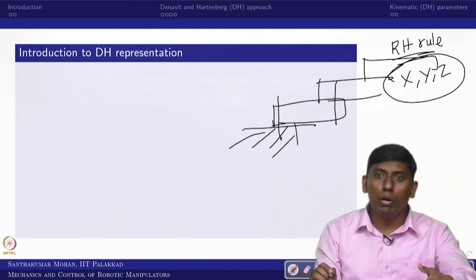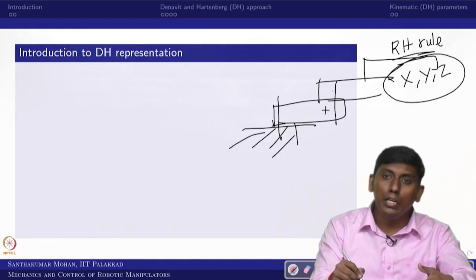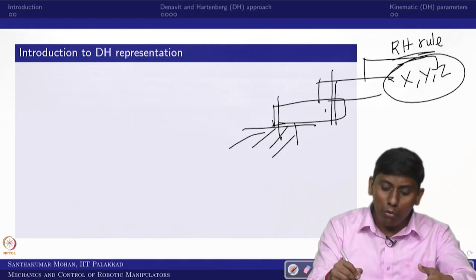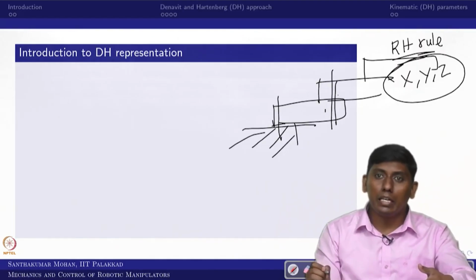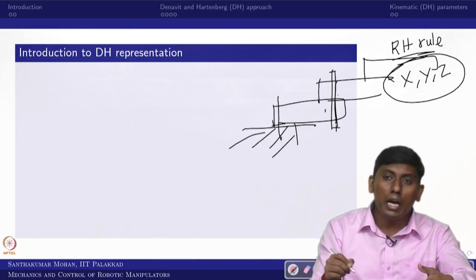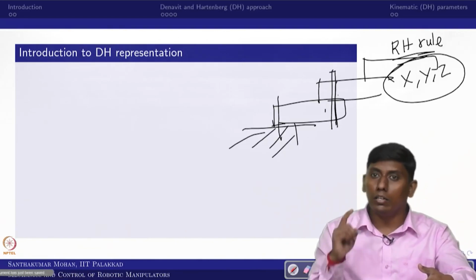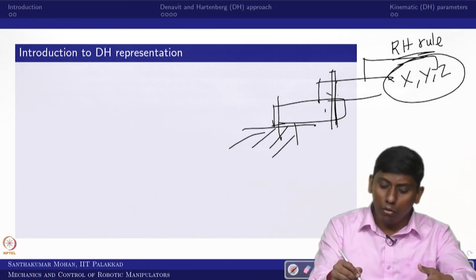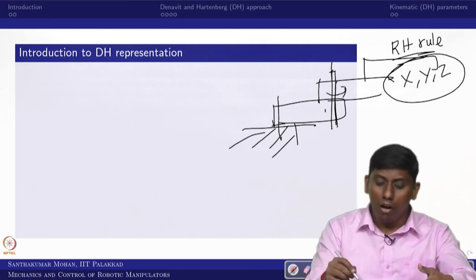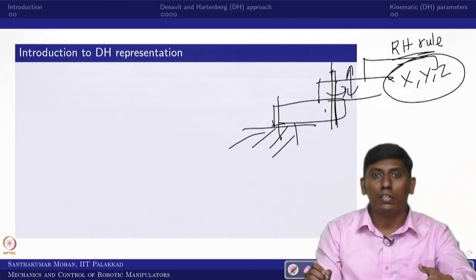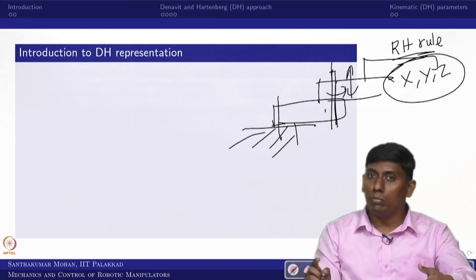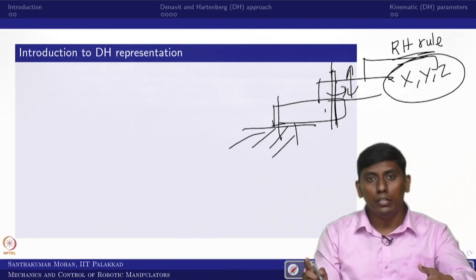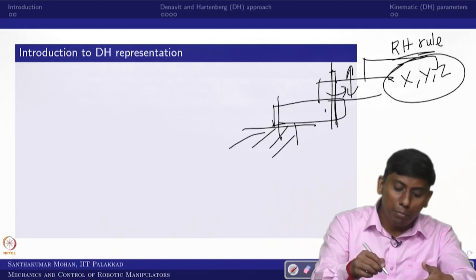So because of that, what happened? So one link to another link is constrained with only 1 joint. Further, what they constrain, this 1 joint would be having, or it allows, only 1 motion. In the sense, this can actually rotate with respect to this axis or translate with respect to this axis. In the sense, so Denavit-Hartenberg indirectly they said you use binary link and each joint would be 1 D of freedom joints. Okay. So these are the constraints which they put.